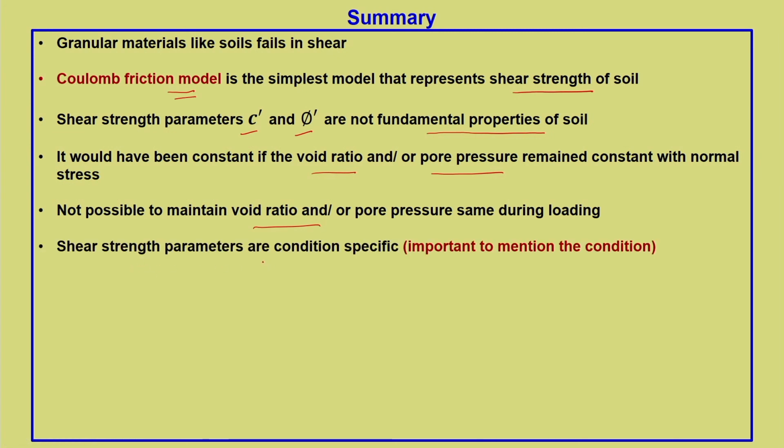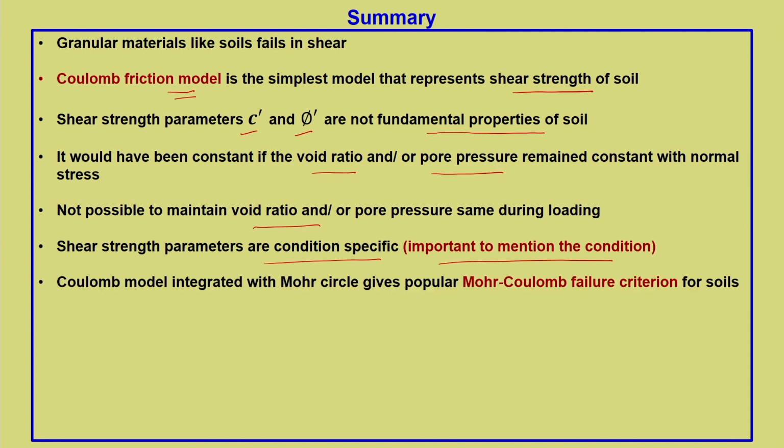So, shear strength parameters are condition specific, and it is very important to mention the condition. Later we will see that under certain circumstances it becomes fundamental, rather it will not depend upon the condition. Okay. So, you underline this particular sentence here. For the time being, with our current understanding, we say that it is not a fundamental parameter, but under specific conditions it can be treated as a fundamental parameter.